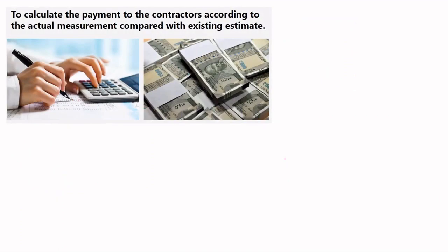Okay, next is to calculate the payment to the contractor. You need to calculate the payment of the contractors, either you are giving weekly, monthly, or once the work is over. It depends upon you and your contractor, right? Actual measurement is compared with the existing estimate.